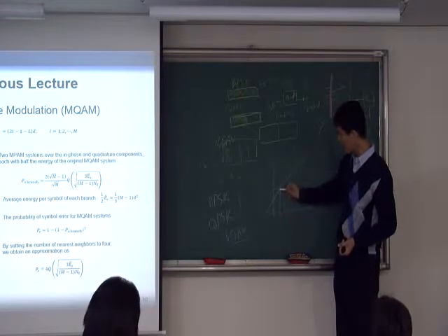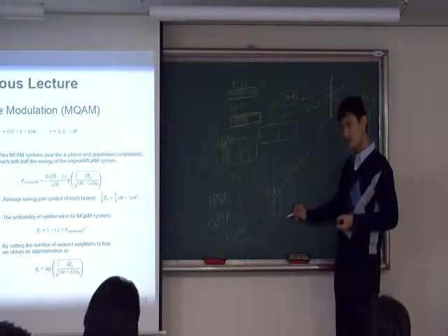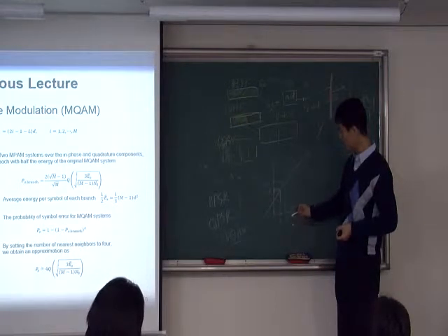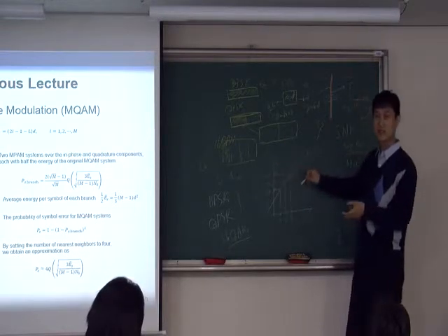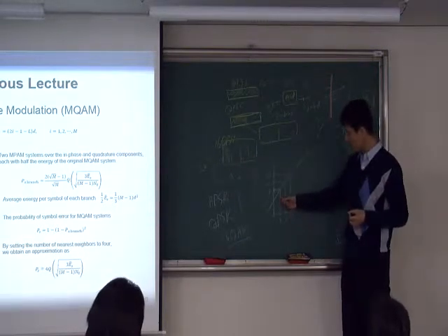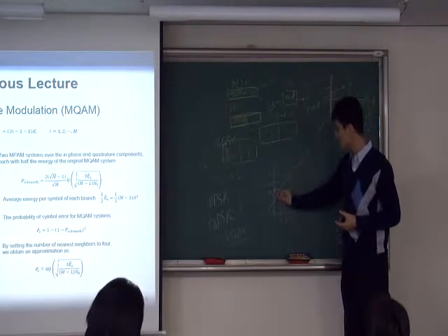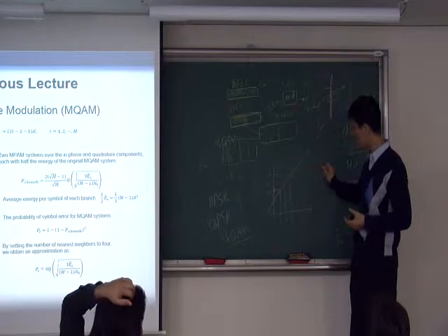Let's say this is 1. It is amplified, and the output of the power amplifier is going to be 10. I'm just giving you an example. And if I have a 2 in the baseband, that's going to be 20. If I have the energy 3, that corresponds to 30 at the output of the power amplifier. That means linear. However, in the power amplifier, typically the device has a limitation such that this linear region is limited. It's not linear forever. Such a linear region is pretty narrow, maybe only from here, and from here somewhere it's going like this.